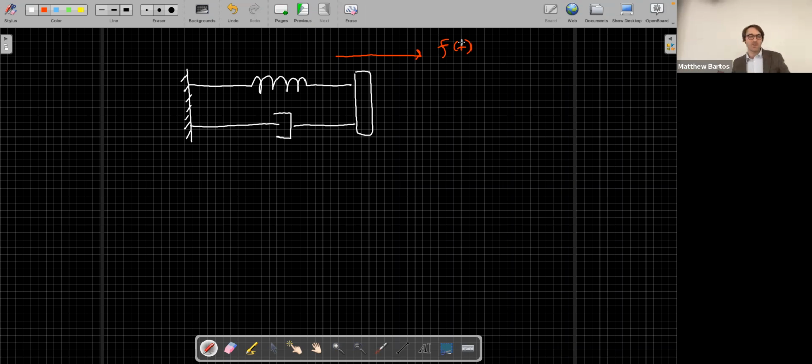So what the integral controller is doing is that if we take this spring mass system and pull on it, the integral controller will pull back with a force that's proportional to how long we have held the spring out. The longer we hold that spring out and the longer we cause the spring to deviate from its resting position, the harder that controller will pull back.